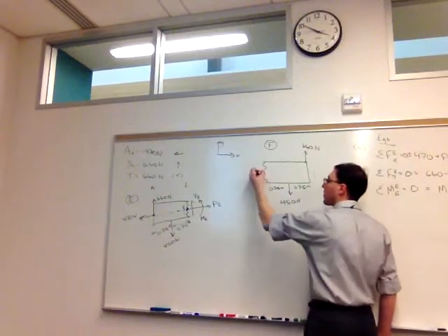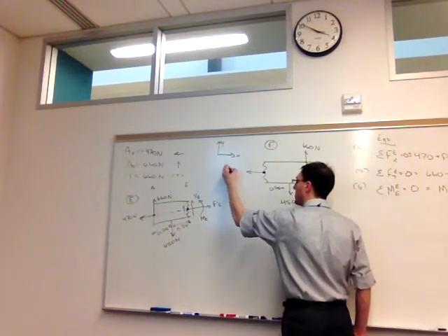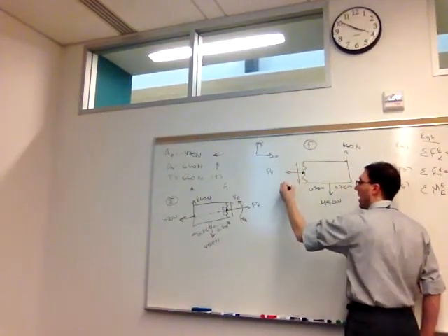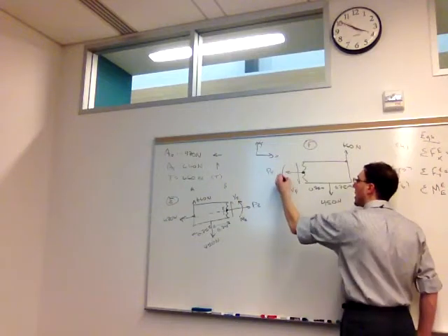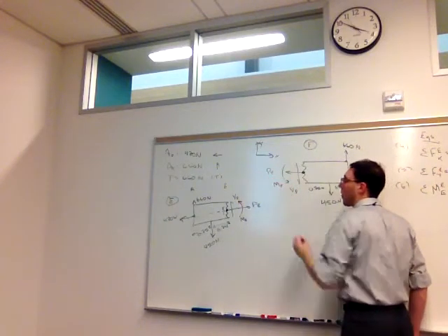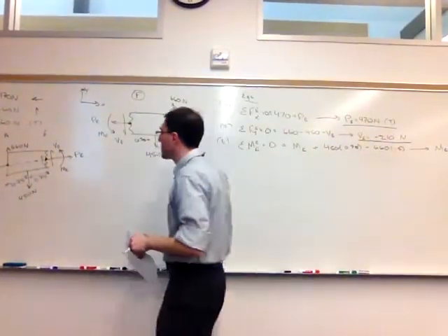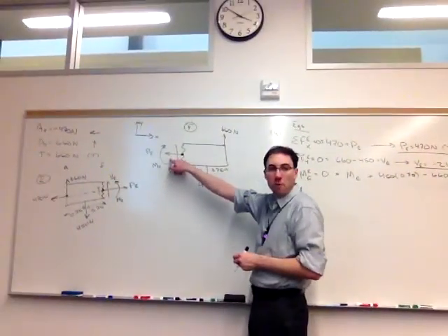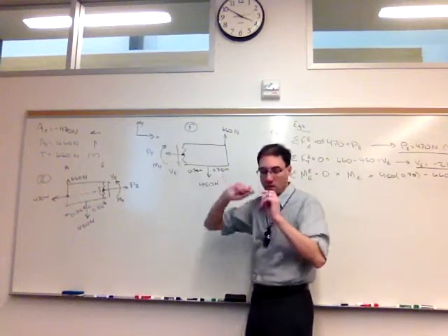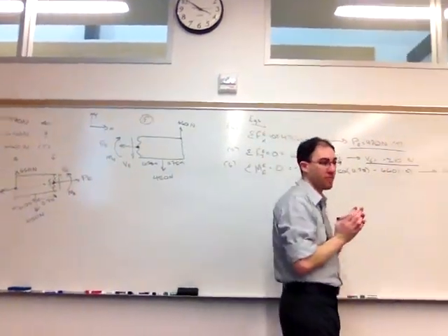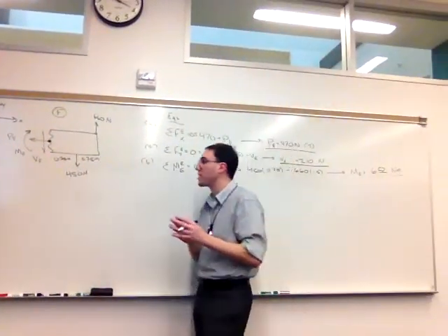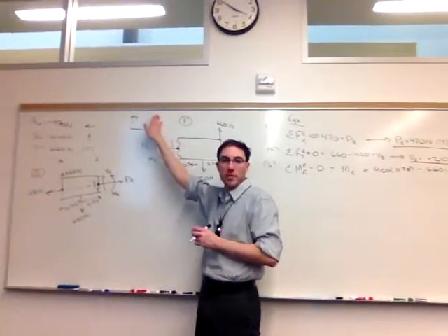And on the cut surface, we're now going to have P sub F. I'll assume VF down, and I'll assume MF counterclockwise. I'll reiterate, our assumption of the direction of the internal normal force has nothing to do with the global coordinate system that we chose.